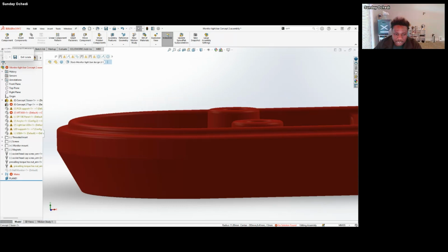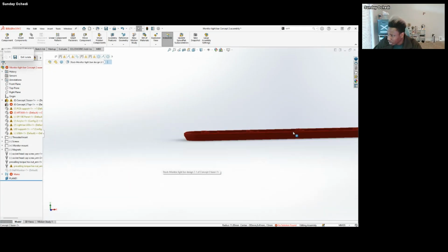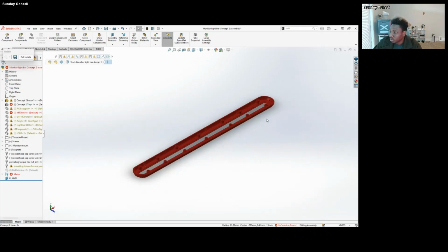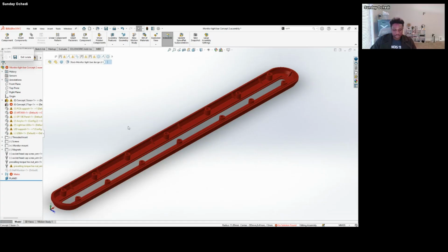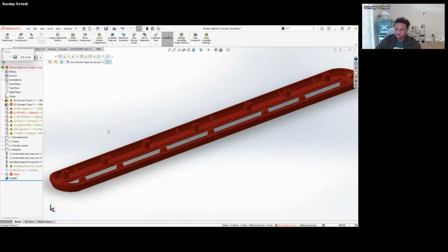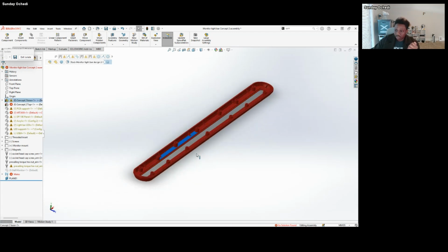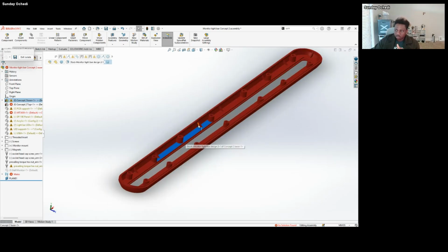And when it comes to determining the rib location, most times it's mainly about what areas are supposed to be stressed. But for my design, if you've noticed, most of the parts are uniform, and I tried to make sure most of them are symmetrical. I know this base doesn't have a lot of stress on it, so I just picked particular spots in between to add the ribs.